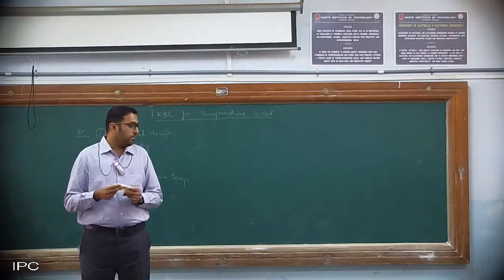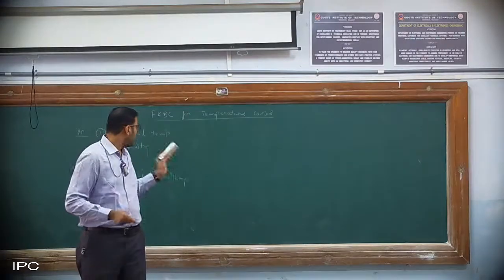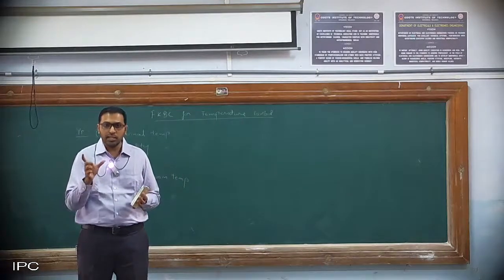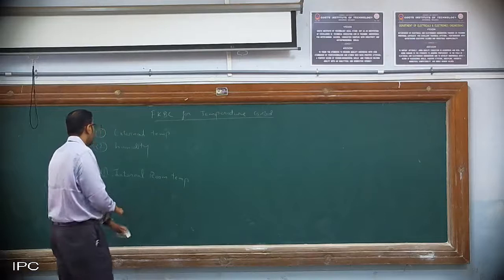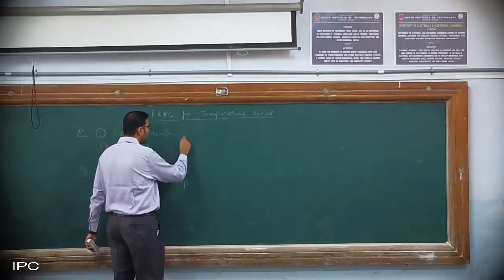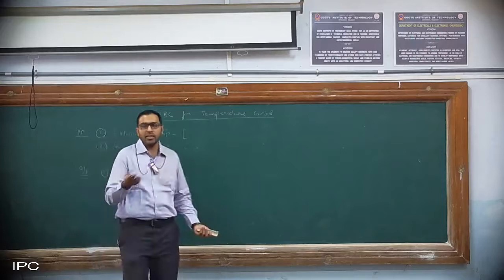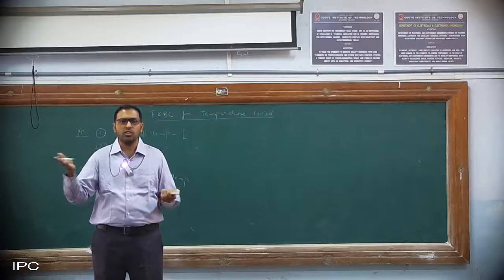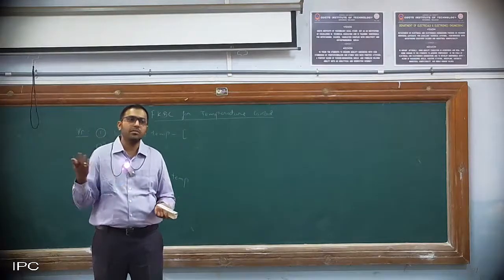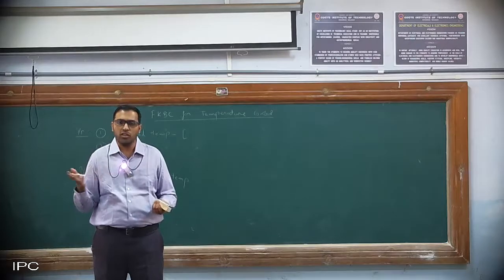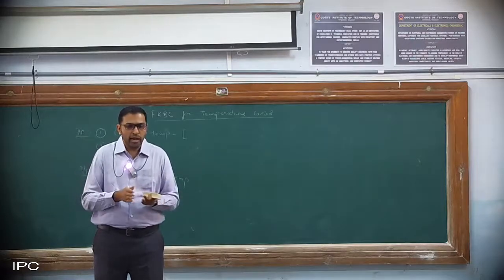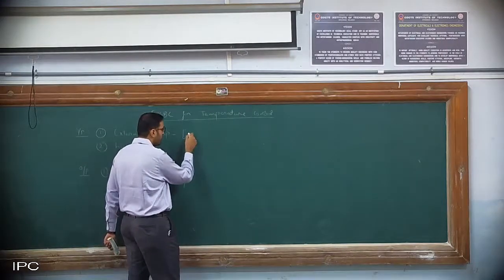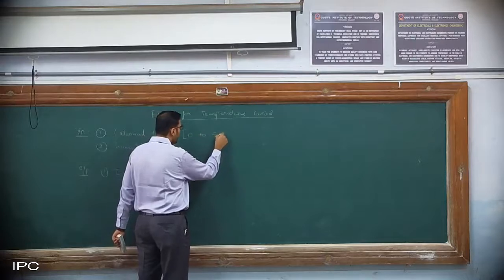Now the next step, we need to select the range. We cannot design a system for an infinite range. So we have to select our range. Take the external temperature. Let us say that if we are talking about the Belgium region, our external temperature varies between 6 or 7 degrees Celsius, which is the coldest temperature recorded, and the maximum temperature recorded was something around 35 to 40 degrees. But in order to have a broader range, we can have a maximum range of temperature for the system as 0 to 50 degrees Celsius.